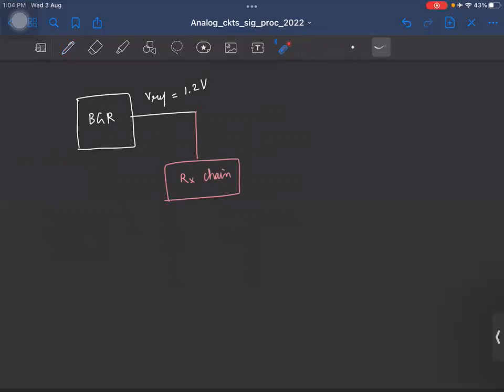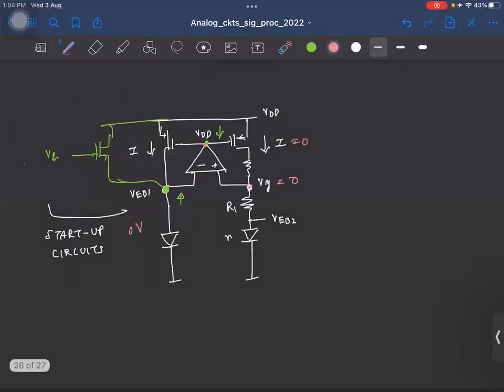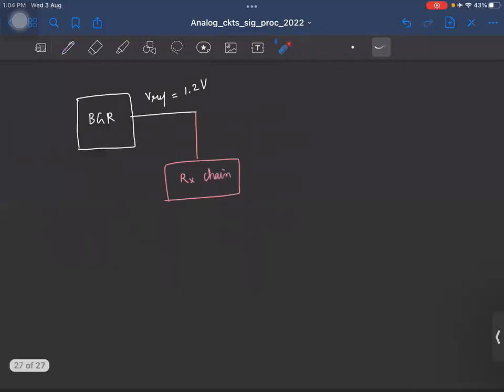No, right? Because see, this is our output voltage. We cannot simply connect some other block, right? Because that will disturb the currents flowing in these branches. So you cannot directly connect this output of the band gap as a supply to any other system. But let us say that is the actual supply voltage I want, but I find that the band gap cannot provide the current for the system. So what do you do? What is the simplest solution?